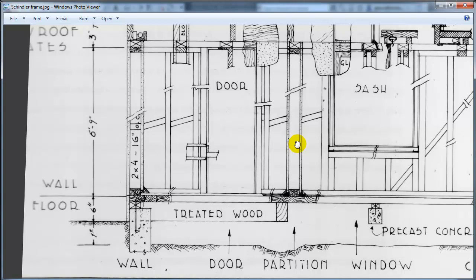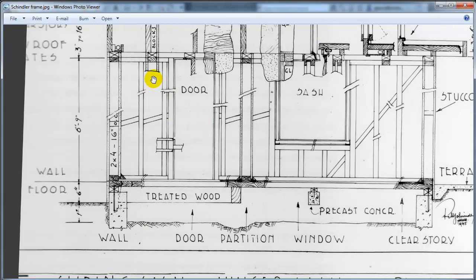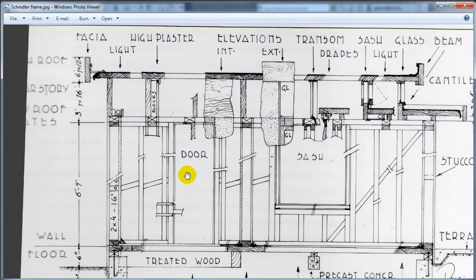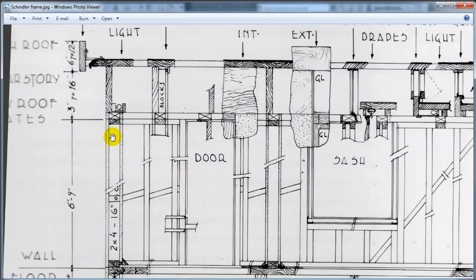Okay. We also have a couple of wall types at the top, and that was part of Schindler's system: he would have these very standard wall conditions at the bottom and just vary the top. The wall would always be about 6'9" to the top of that first plate. Then there'd be a base plate for the top wall, covered with stucco or plaster too. So I'm going to model a little bit differently. I'm going to model the 6'9" plus the continuous top plate, so 6'10.5" tall.